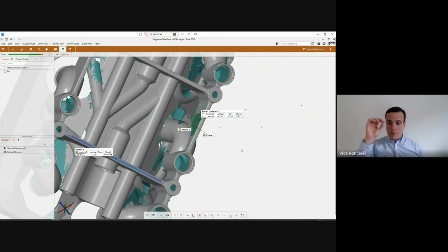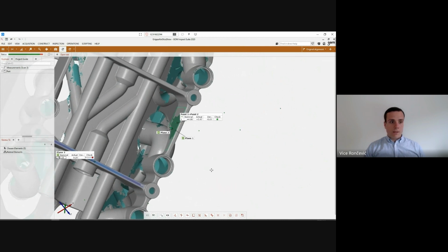We assign 2 points on these two fitted planes, and we measure a distance in between them. This distance is internally constructed as a two point distance. We find that there is a median plane, which is not visible here in the GOM Inspect, and two perpendicular lines that are intersecting this median plane are then drawn from point 1 to point 2 to give us our distance. Essentially, these two planes from both sides of our measurement are what your caliper would get when you press it tightly to both of the surfaces.